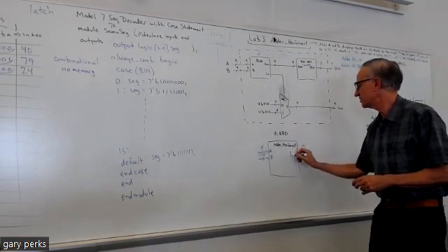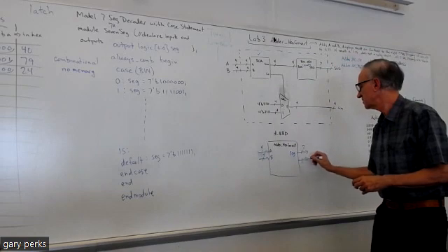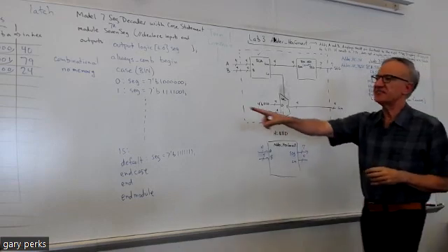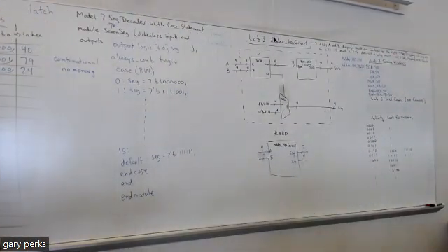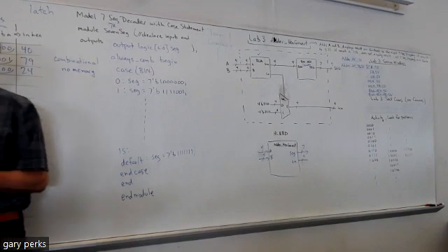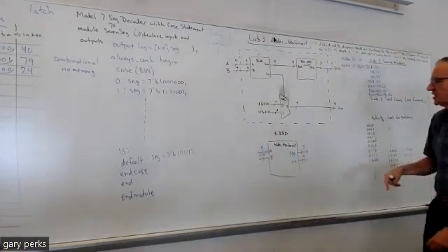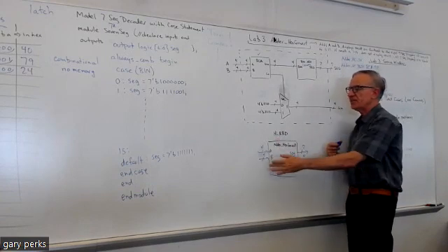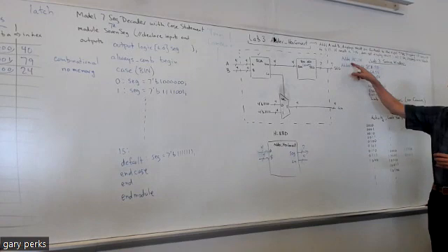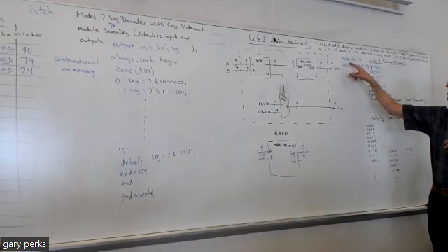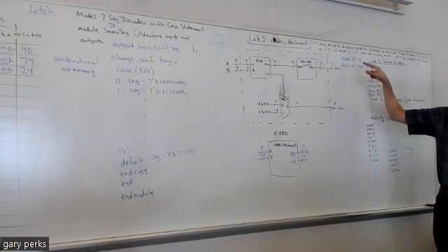The seg is 7 bits. AN is 4. Okay, so remember, AN, that's the anode input. AN determines whether a segment is going to light at all. And then the seg, that's the cathode bits, right? That determines which segments light. Okay, so that's your high-level black box diagram. So remember, the high-level black box diagram gives you the inputs and the outputs that you have to declare in your overall structural design, right? So that's going to be the inputs and outputs that you declare in these files here.